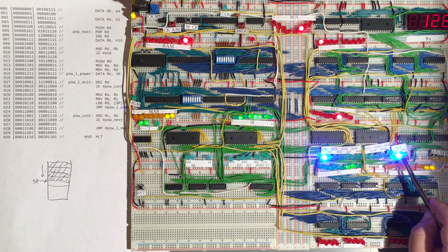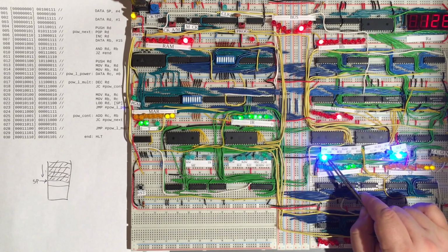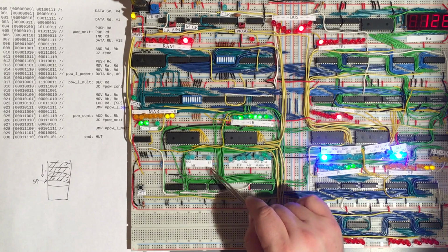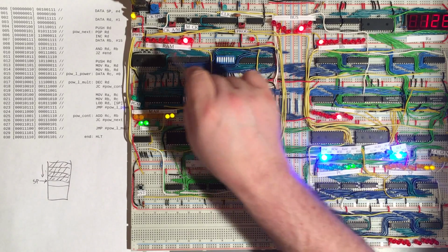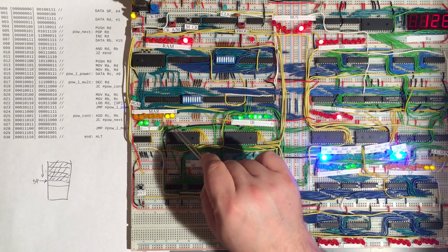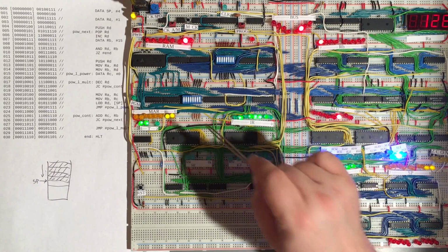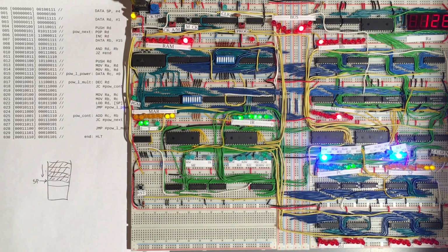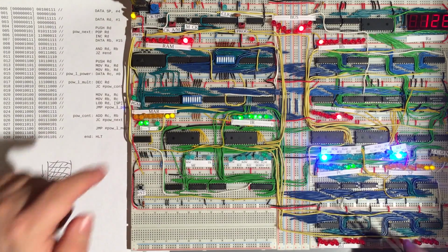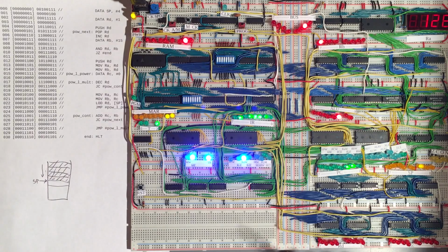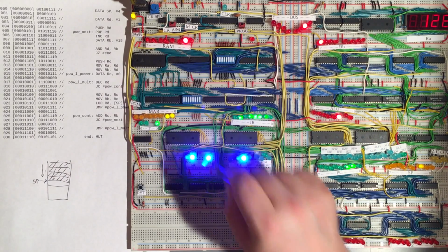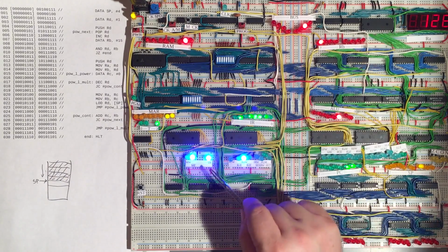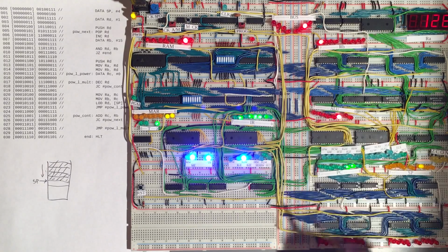And so the contents of the ALU are at this moment on the bus, and so we'll write those to the stack pointer. But of course this isn't the end of the instruction, because we still need to get the value from RAM, which is now being pointed to by the correct old value of the stack pointer, into whichever register we're popping into, and so in our case that's this D register. So after this cycle completes, after this 4 goes into the stack pointer, we still need to do one thing, which is to get this value from RAM, so we enable RAM out back into the D register. And so we have the D register write enabled, and so then that too will go here into the D register, and that is the end of our pop instruction.